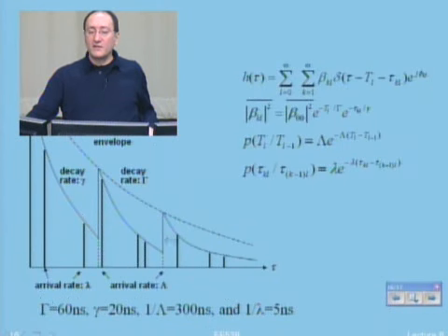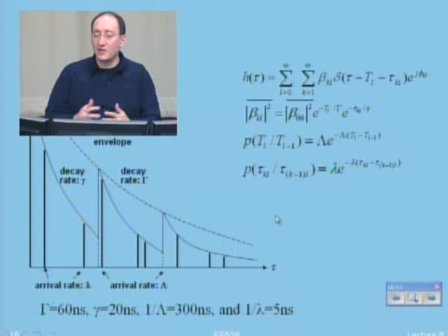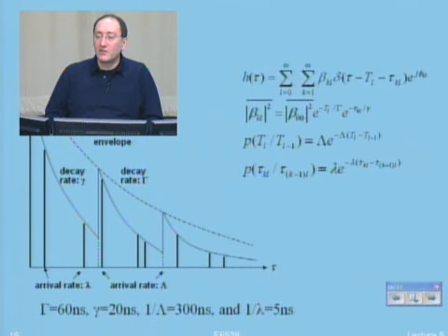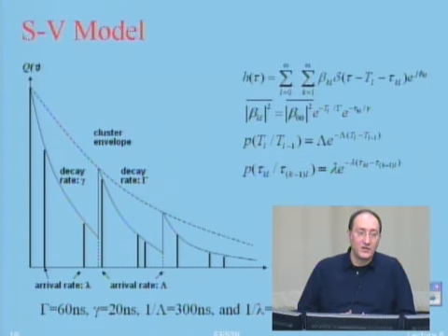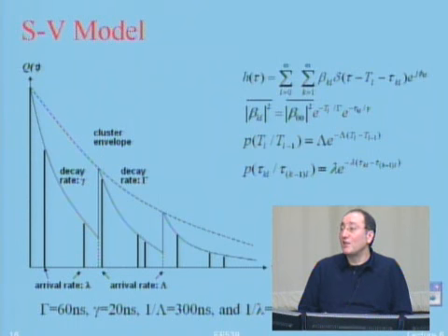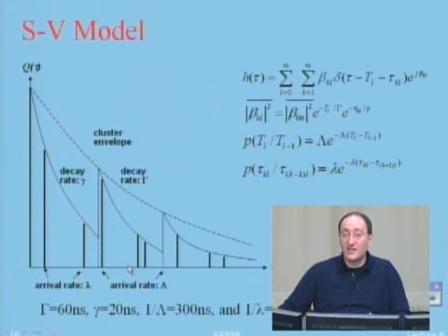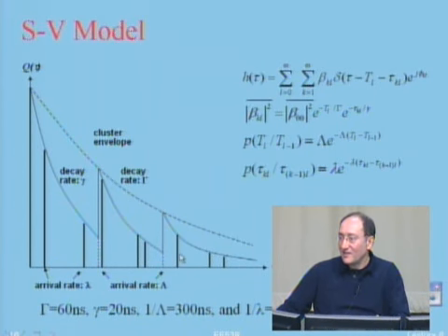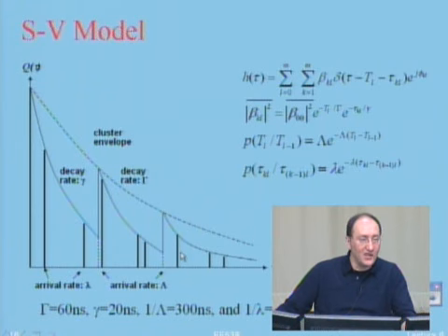Now, what was important of this thing? How did this thing come up later on? Later on, people started to think about modeling for MIMO. So modeling the angle of arrival. And when you want to do the angle of arrival, again, they use the cluster model. So the beauty of Saleh-Valenzuela model, which remains there, is clustering. So if I have a bunch of arrivals, if I associate each arrival to an angle, then I can give a distribution for angle of arrival to them.